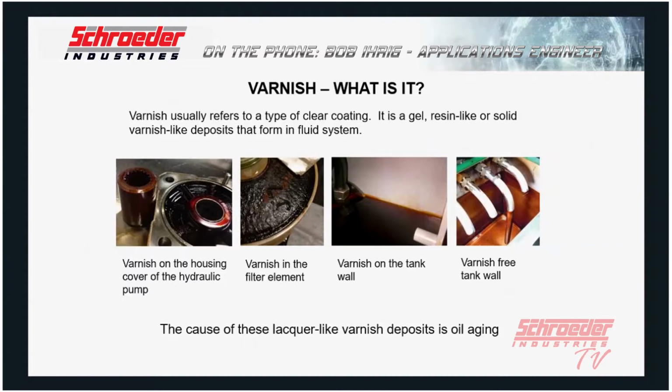So, varnish, what is it? Varnish is a generic term for oil degradation byproducts, quite simply. I kind of want to demystify it a little bit. It's pretty much just the byproducts of aging. And it doesn't sound like a big deal, but whenever it happens prematurely and it damages components and reduces the service life of a system's fluid and its components, it's obviously an issue.